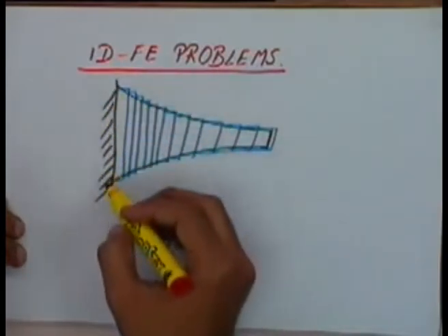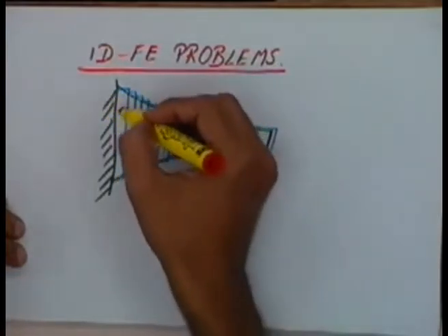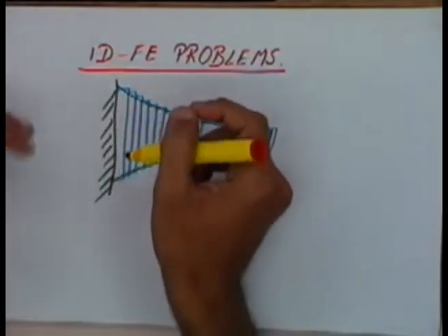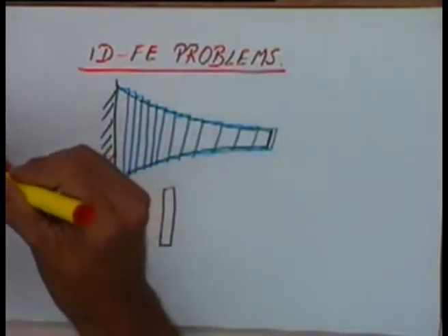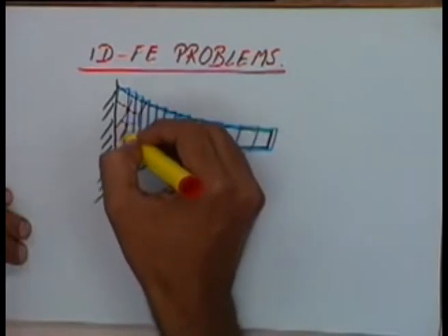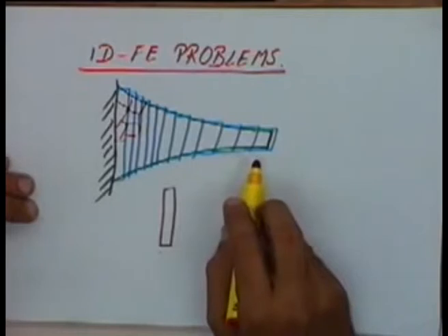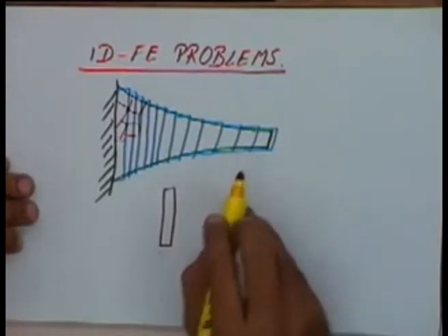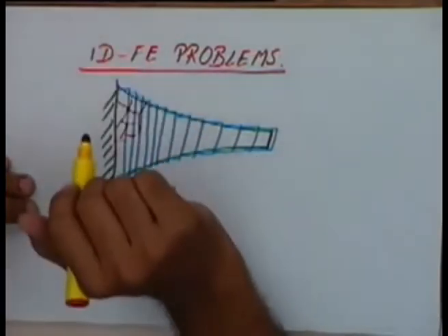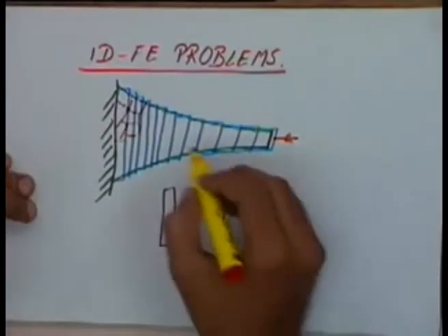If we want to formulate the same thing as a two dimensional problem, then we can approximate it by triangles or quadrilaterals or something like that. Those could look maybe something like this. But right now we are just talking about a simple one dimensional formulation of this problem. So we will assume that there is no variation in the other two dimensions and all loads are also only acting in one direction. All the loads will be acting in the x direction only.